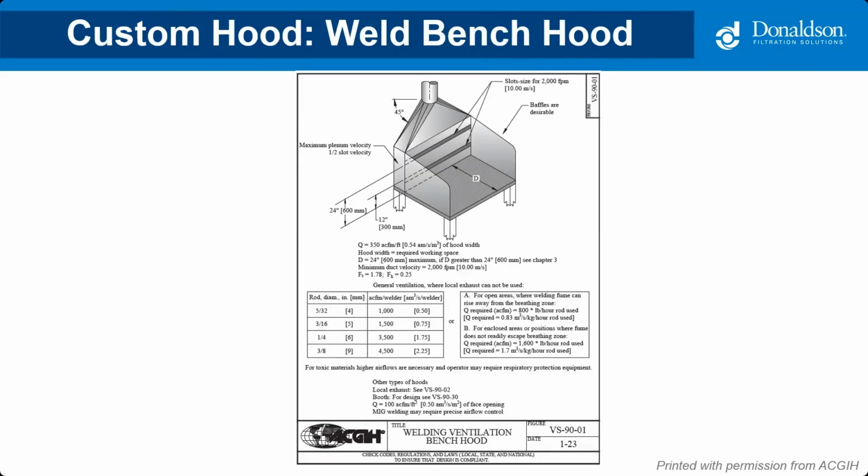Again, the VS manual is very useful for helping determine airflow and static pressure at the hood based on the application. We also have some products, and these are great tools that show you how to calculate exactly what you need. Donaldson, for example, makes a weld bench hood that has all this math built into it with a prefabricated hood. Same with the extraction arms on the previous slide. We offer those same hoods as well, with everything built into the design.